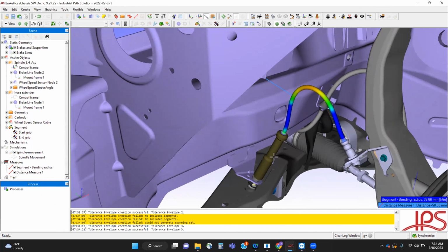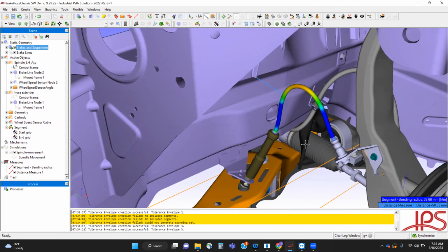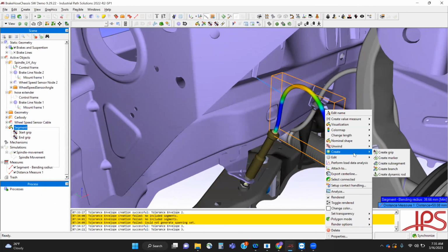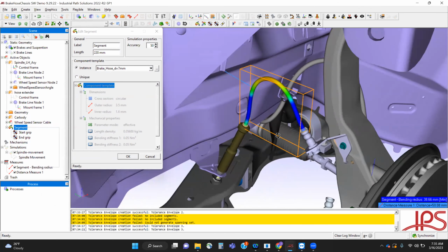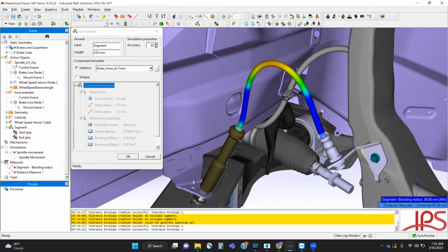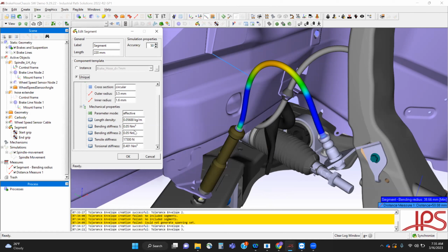We have another question from our attendees. Wire harnesses have many different coverings: spot tape, protective tape, sleeves. How are you accounting for that? Yeah, that's a great question. In the IPS tool, what we're trying to do is look at a high level at the physical behavior of these flexibles. So based on your material properties, those would take into account the various coverings.